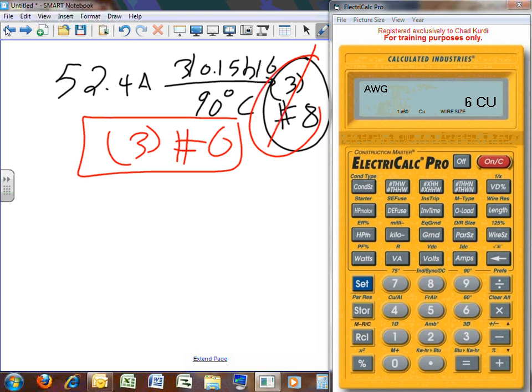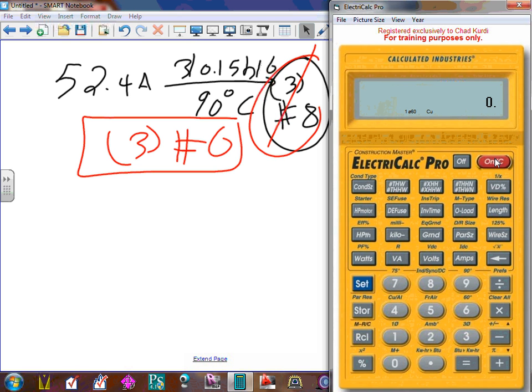Okay, so let's go use this calculator, guys. Here's how you do that. Do you remember what our situation is? We have 43 amps, right? First of all, put in your 43 amps. Up to this point, nothing has happened. It's copper; it defaults to copper 60.